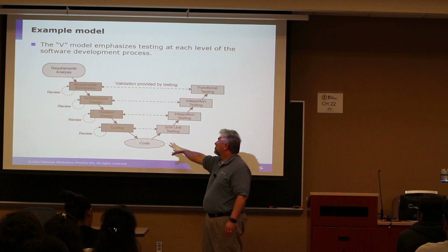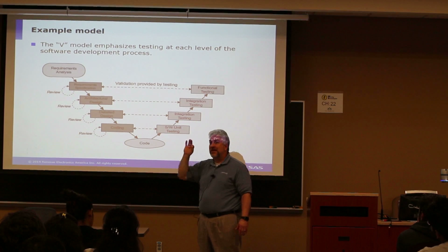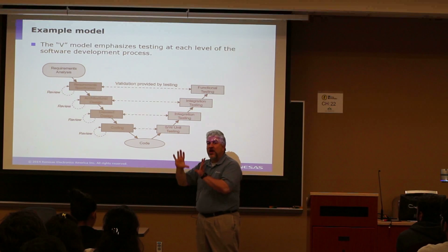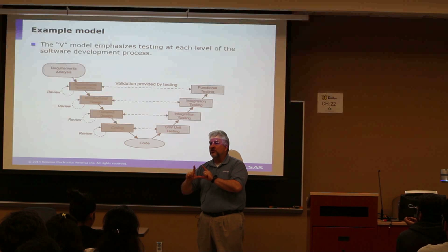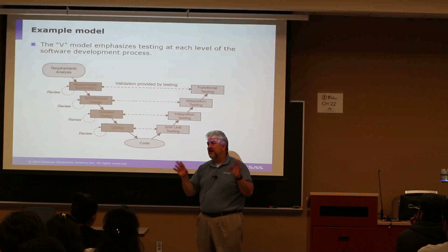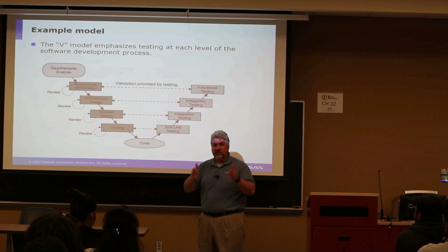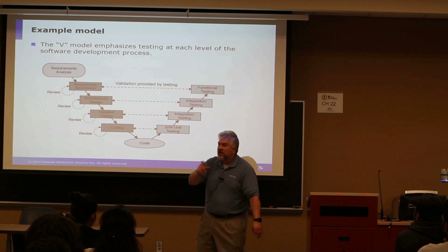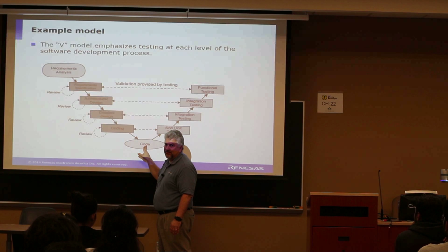Now, this shows just software, but very often at the same exact time, you're developing the hardware. And sometimes you have, like the Renesas board, an evaluation board that allows you to write some software and kind of pretend that you have a hardware system. And sometimes that's all you have because somebody is developing the actual hardware product, and they're going to be done at about the same time that the code is ready.